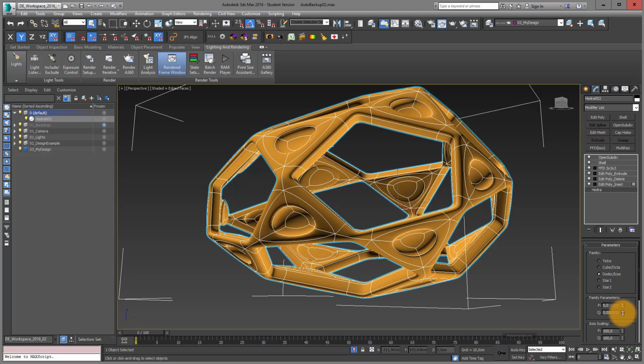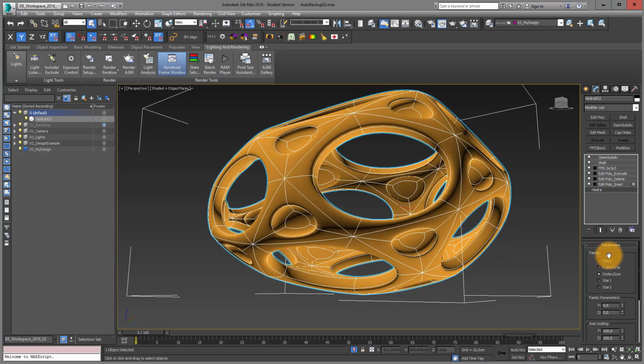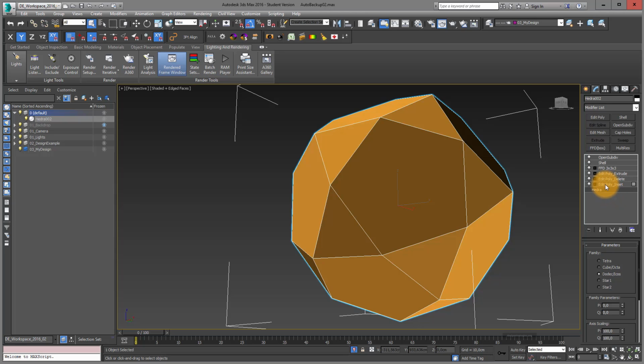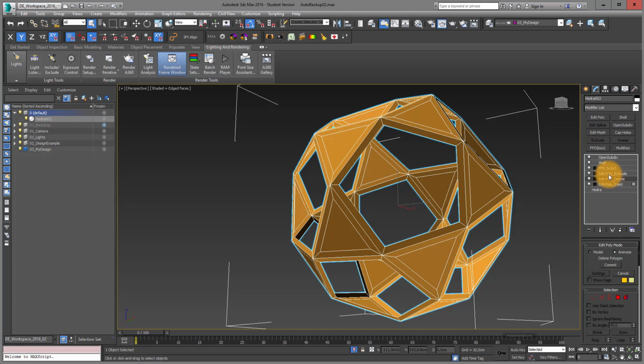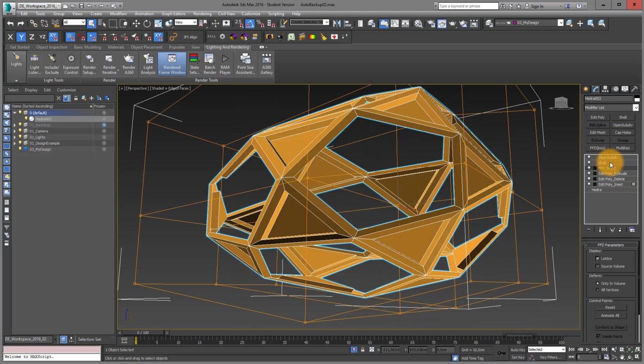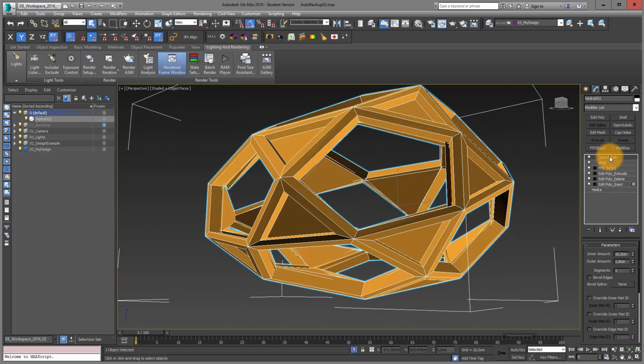And you can imagine that 3D Studio Max is a little bit like Photoshop with layers. So you have modifiers and you can stack these modifiers on top of each other. Most of the time you start with a really simple shape. You add these modifiers on top, and I just go through this modifier list.